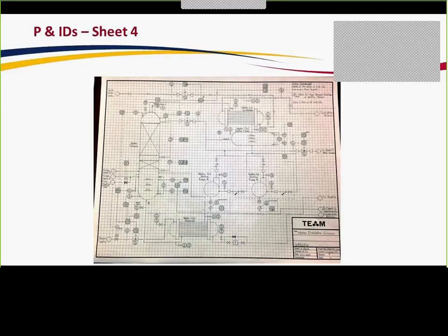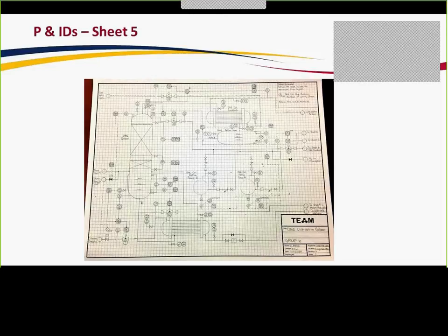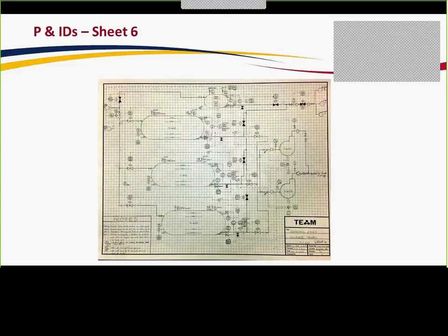We included an online analyzer as well as pressure and temperature to control the composition leaving the column. We used a similar one for the DME, where we controlled with an online analyzer the DME product going to the storage tanks. Lastly, for our storage tanks, we used a high-level indicator with an interlock system to shut off the valve going into the tanks to prevent any overflow.